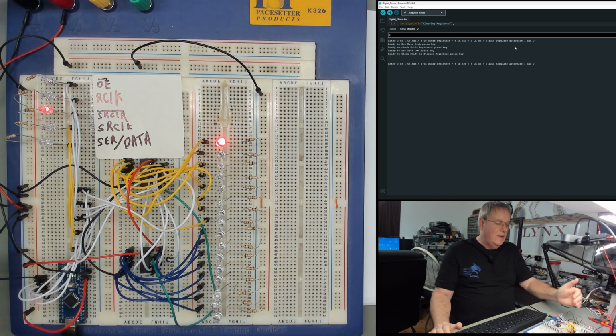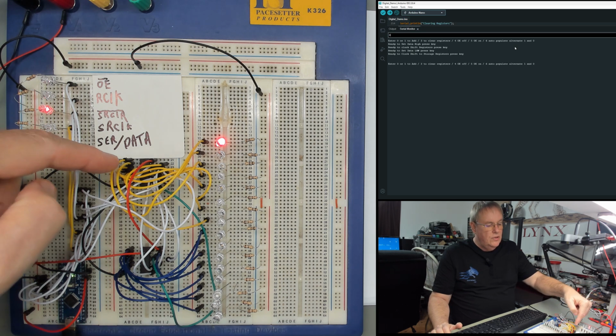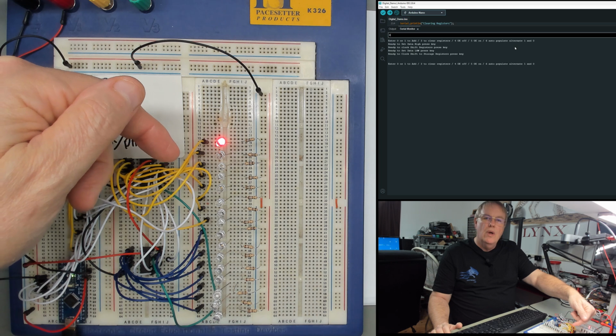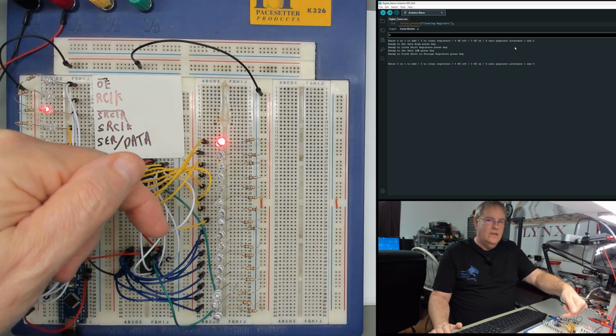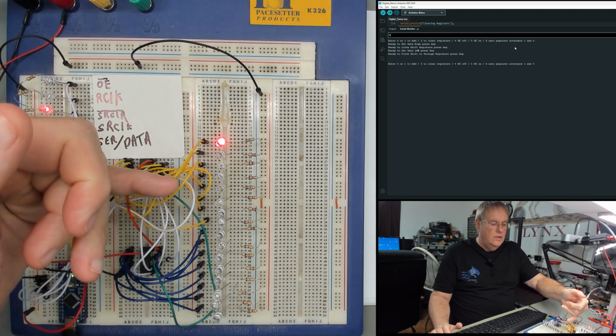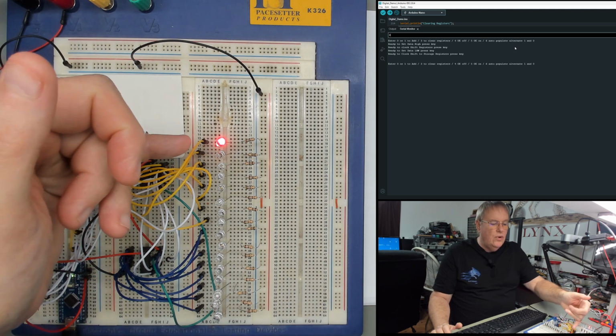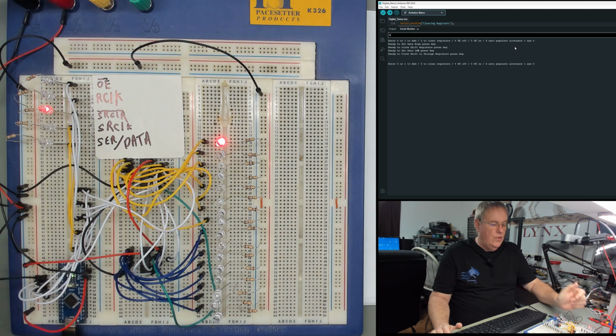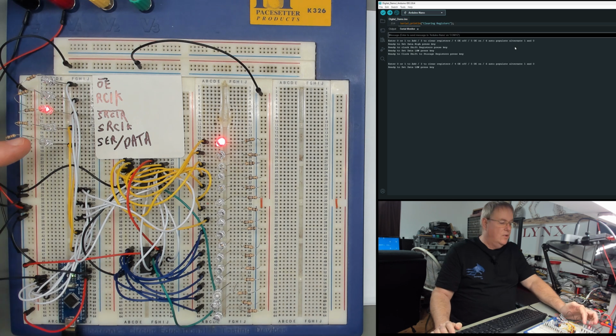And what's going to happen is that same action is going to happen again, but we're going to clock a 0 into the first register, which will push the 1 we put in into the second register. Again, they're shift registers. We're going to shift this 1 to the register 2 and shift the 0 into 1. This is going to move. I put a 0 in, enter. Ready to shift, set data low. Data's already low, but it's going to set it low.